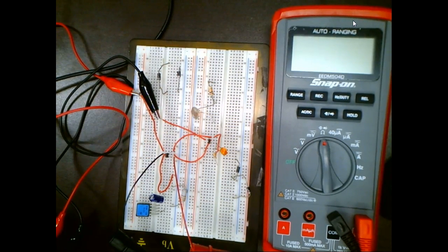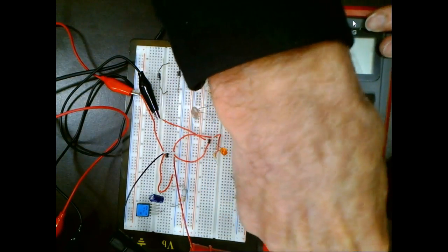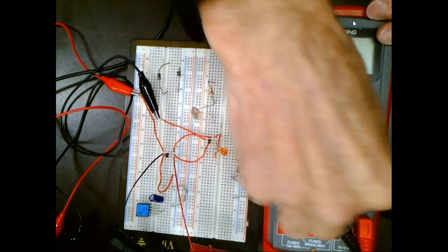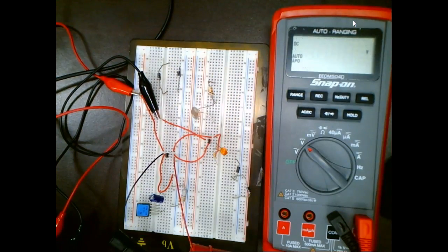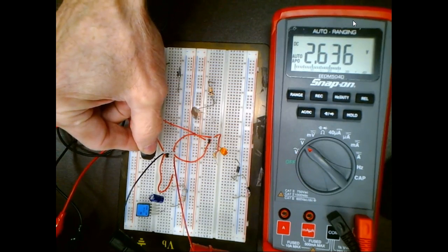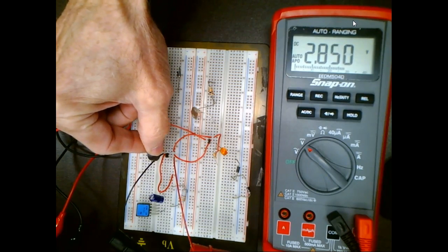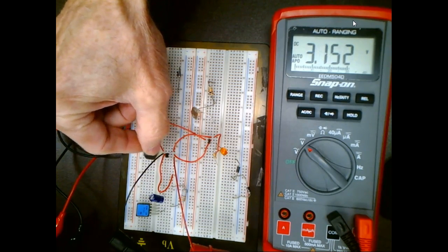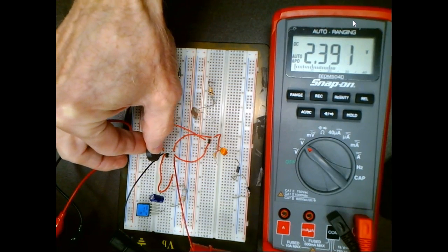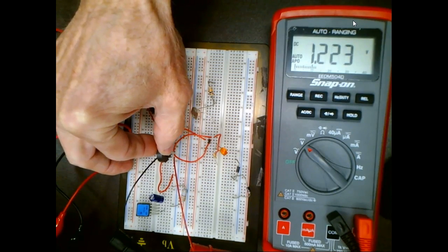This guy is right out there, so it's going to give us a voltage. It's going to tell us what voltage. Sorry, maybe we have to turn it off to get it to come back on. I've got it across my Hall effect. Right now it's dropping about half the voltage, the way this is designed. I'm going to start bringing a magnetic field in, and what do you start seeing it do? Here it's going up, right? I'm going to flip it around and give it the other pole, and look what happens. It goes down.